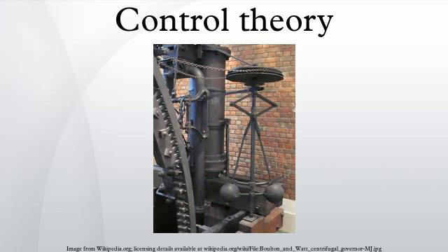A primitive way to implement cruise control is simply to lock the throttle position when the driver engages cruise control. However, if the cruise control is engaged on a stretch of flat road, then the car will travel slower going uphill and faster when going downhill. This type of controller is called an open-loop controller because no measurement of the system outputs is used to alter the control. As a result, the controller cannot compensate for changes acting on the car, like a change in the slope of the road.